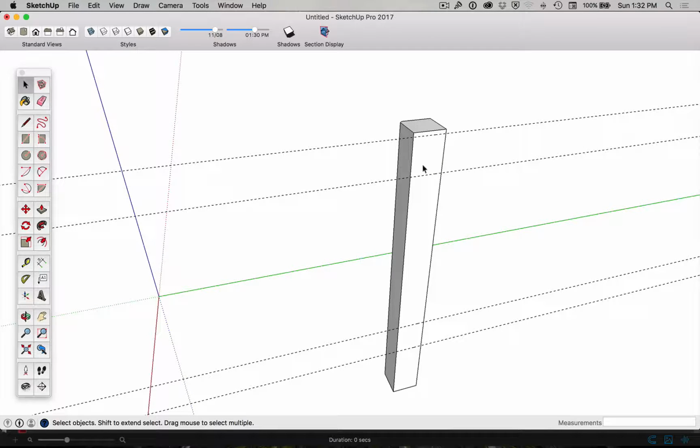And now I want to go in from the, what can I do here? I've got a 10mm mortise width in the center. Now if I know that's 40mm from there to there, and 10mm is what I'm after, if I went in 15 from this side and 15 from this side, that means the middle bit, because 15 and 15 is 30 and it's 40 altogether, then the middle bit must be 10.